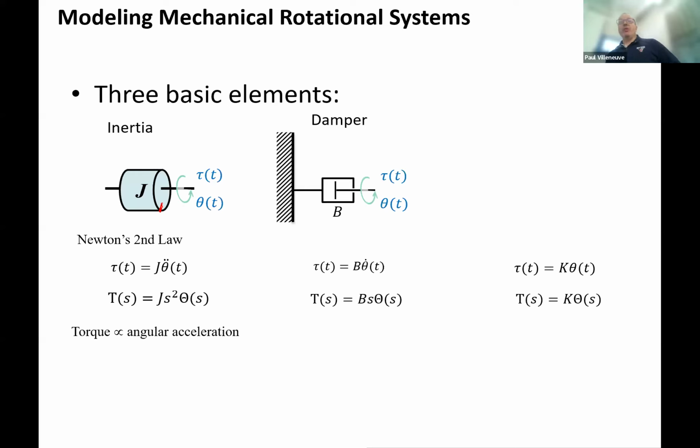A damper. We do have dampers, and they're pretty easy to make, just as rotational. So the ports, instead of being lined up when an object is moved in a straight direction, would be lined up as the object is rotated around. So it's almost like a paddle with some holes drilled in it. It'd be something that's spherical in design, and you just port oil in that direction. So exactly the same concepts where you have that oil going through the ports, and that would be viscous, which is another way of saying fluid, viscous friction.